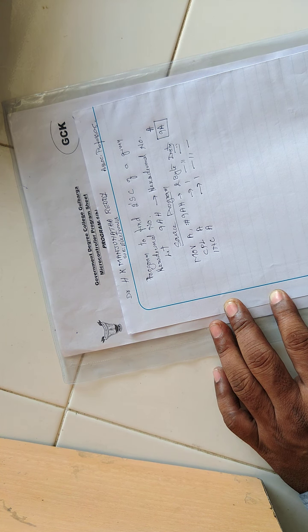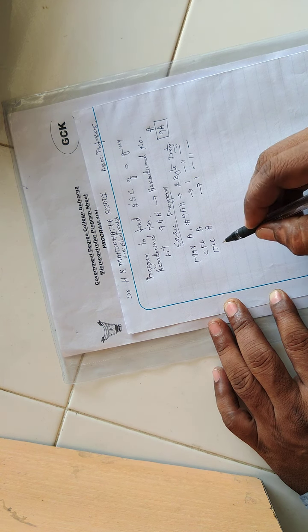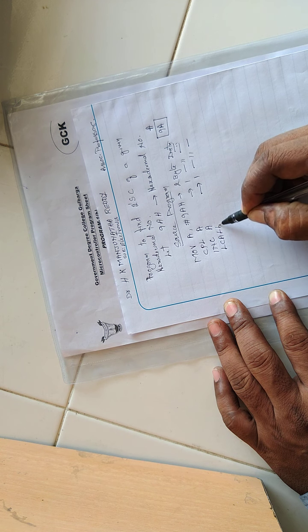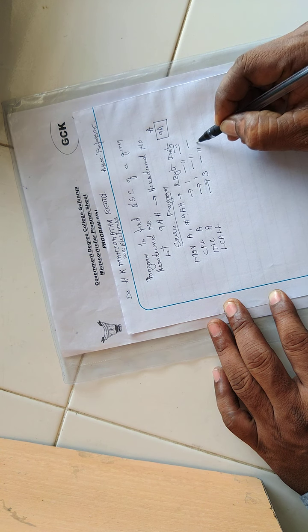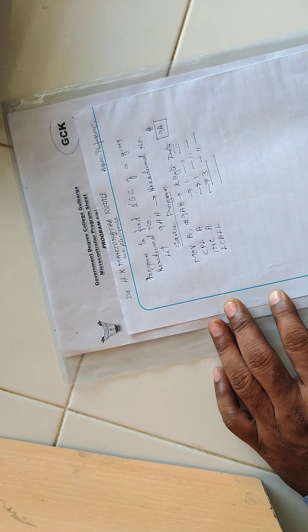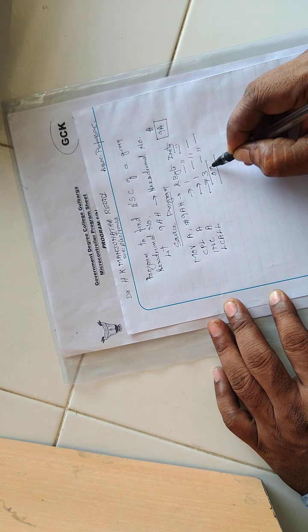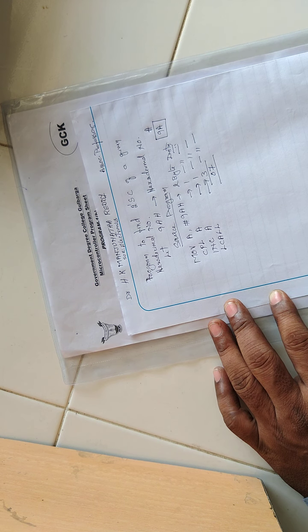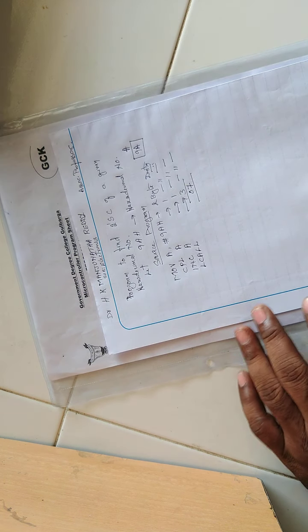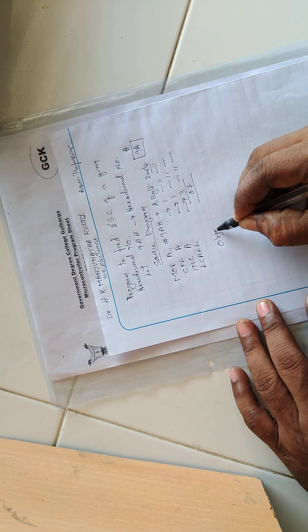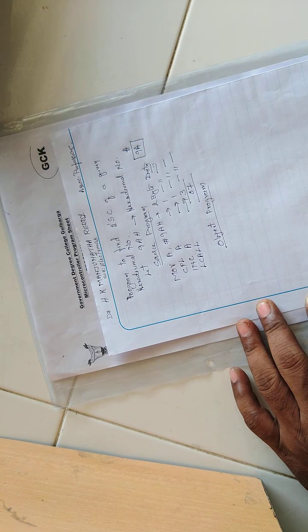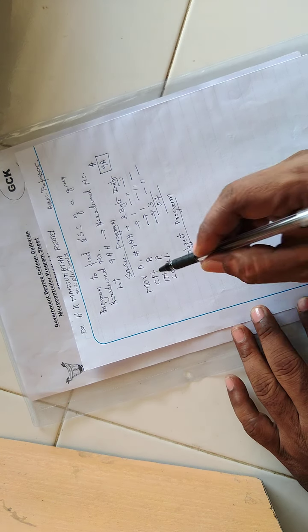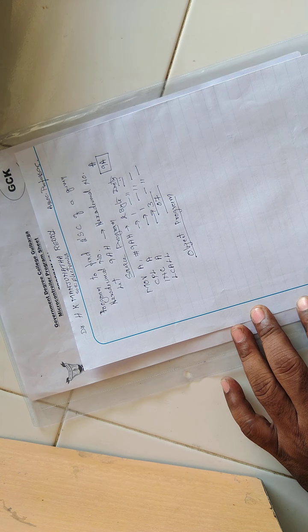Well friends, this completes the process of writing a source program to find 2's complement of a given number, but always the program is ended with an instruction LCALL, which is a 3-byte instruction. Total number of bytes required here is 7 bytes of memory location to write this program into the RAM. The actual program fed into the processor is in the form of object program. The same thing, we shall put into the object program format.